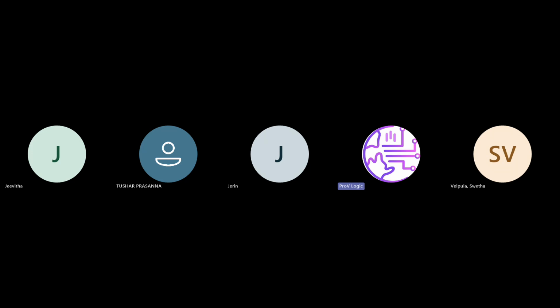We create the object for the class. Whatever these 10 variables are there, we put them into the class. By using the object, we use a single method, just object.randomize for the transaction class. By using just a single line, we can even randomize 100 different variables at a time. So that is the benefit of SystemVerilog randomization. We can even control the randomization there.